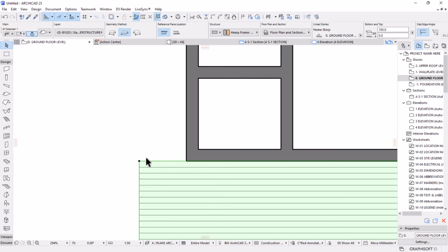Let me redo it again. If I click this point and then add the polygon, you see here, this will also determine the way you want to add another section or extra content to this slab. So I'm going to use this rectangular method. Let's see how it works. Just like that, and then place it all over by somewhere there. Perfect.